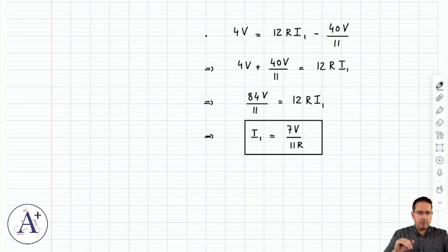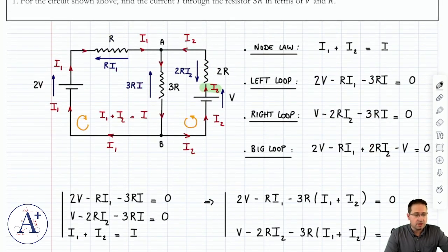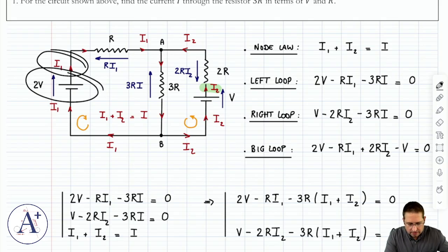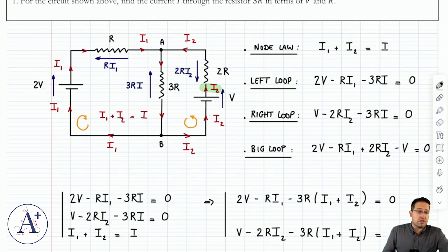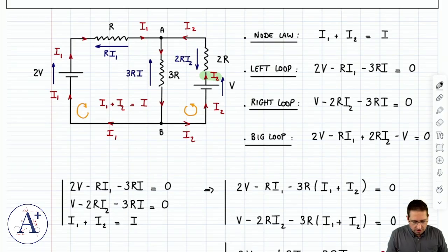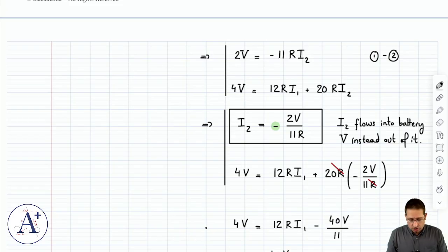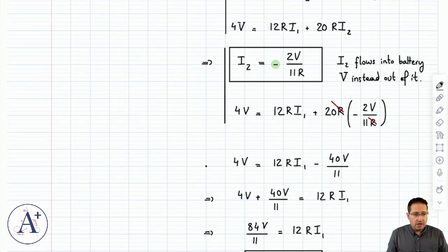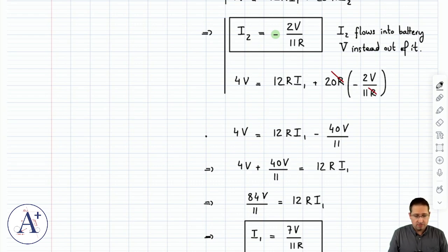By the way, I1 is positive. That's math telling me that my initial guess to draw I1 coming out of 2V is actually correct. Of course, I already knew that, because if I2 is going back into V, the other battery better supply power to the circuit, otherwise nothing's happening. I can't have two batteries magically charging and nothing supplying energy. But the point is, you can guess I1 and I2 in terms of direction initially. You set everything up. If you're wrong, math will tell you, you acknowledge it, and you carry on with I2 being whatever solution came out negative.